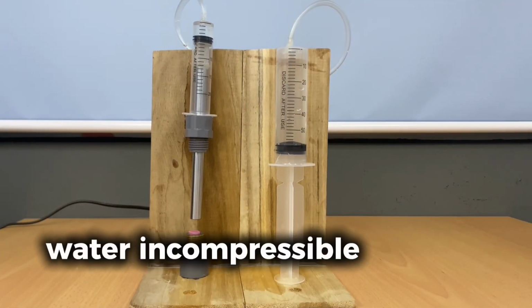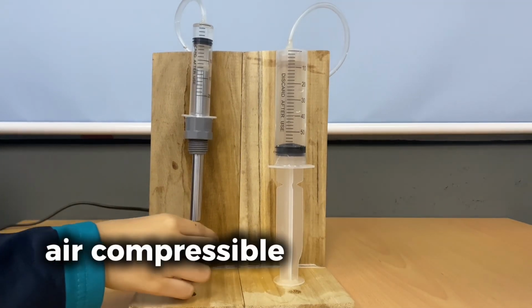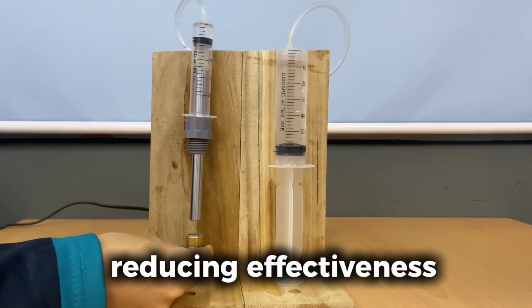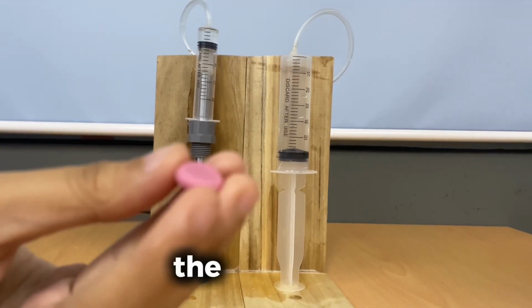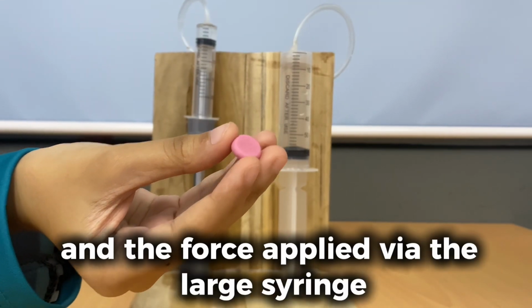Water, incompressible, transmits pressure efficiently. Air, compressible, absorbs some pressure, reducing effectiveness. The amount of compression on the plasticine depends on the size of the plasticine, the fluid used, and the force applied via the large syringe.